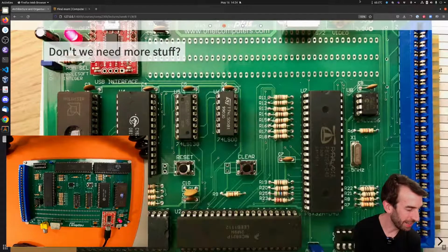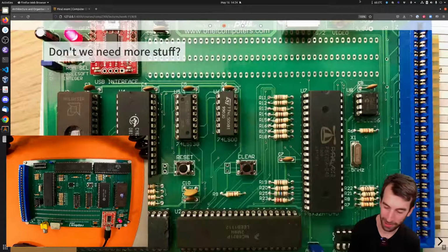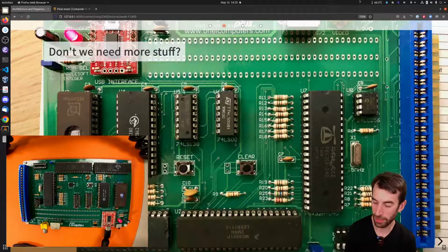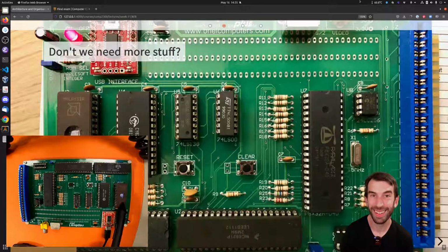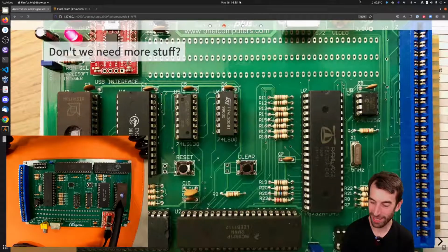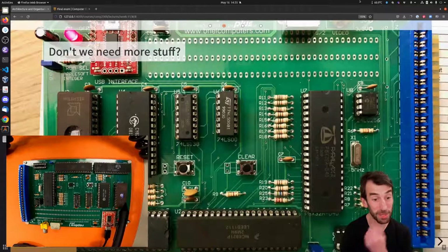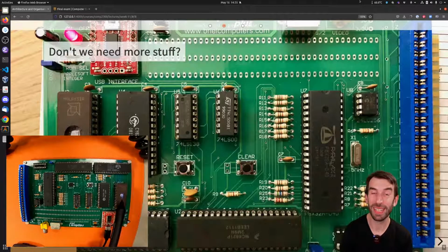What we've got here, and I can just talk about all of the things here. This chip lets me interface with it over USB, so it's providing a serial connection. That chip is memory, regular RAM. This chip is non-volatile storage, ROM. You can see it's got a little window here because it's an old kind of ROM. Before Flash, there were ROM chips, non-volatile memory chips, but you had to go through a fairly detailed procedure to erase them, which is to put a strong ultraviolet light into that window for about 10 minutes, and that will erase it, maybe less than 10 minutes.